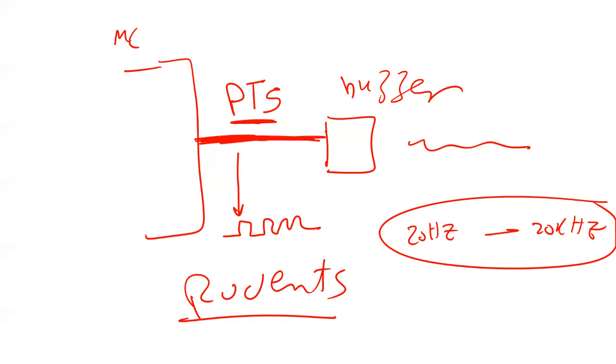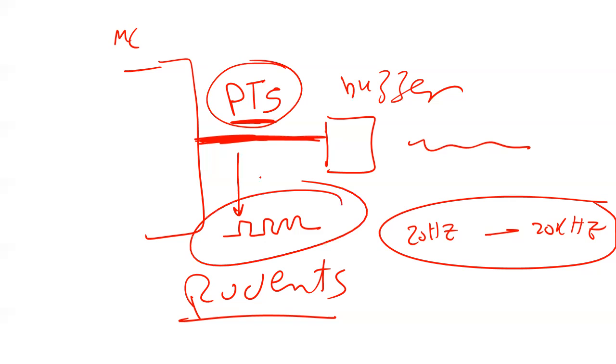But the conclusion is we have a buzzer that's connected to BT5, and if you want to generate a sound, all you have to do is generate a square wave. Very easy. I already explained how you can generate a square wave. Very trivial. Is that okay? But you have to select the frequencies correctly, because some frequencies we cannot hear.